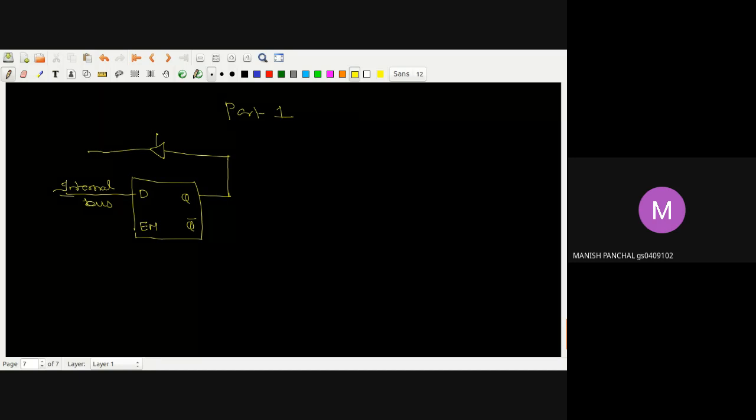So if I want to enable this, what do I have to do? Suppose this is my input terminal, this is its input terminal, and this is its output terminal. Until I enable it, my input will not appear on the output, because it is a type of tri-state buffer. So here I have to give the proper logic level for the input to flow to the output. This enable pin of the tri-state buffer is called the read latch. Whenever I give read latch as 1, the input will flow from input to output. Okay, is it clear?